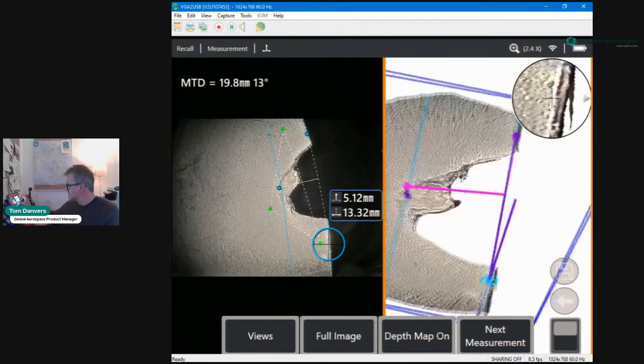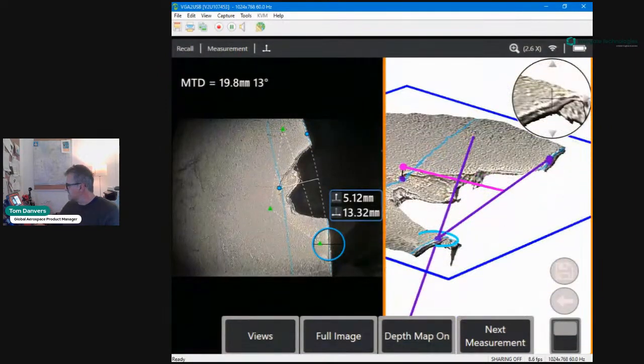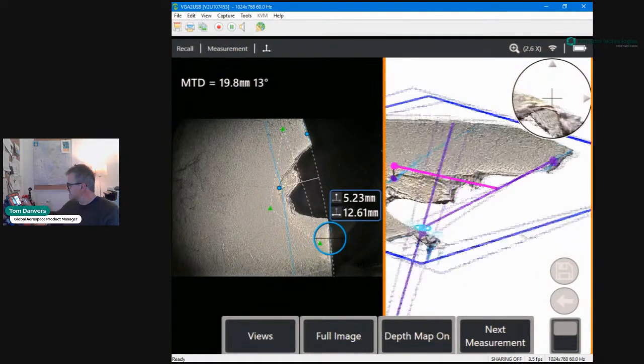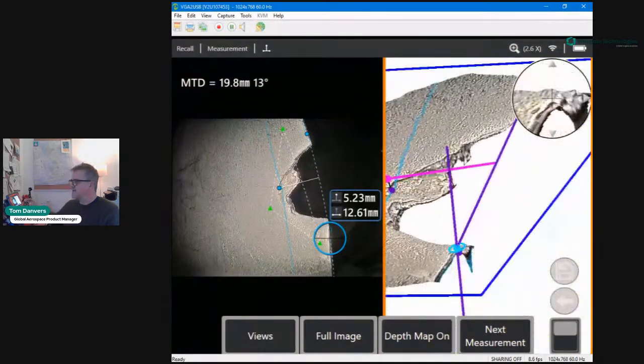And this is where you can work in the point cloud, and the use of guidelines is really important here. Less so on this blade, because this is a very thin sheet metal sort of surface, but we can talk about guidelines when we move to other measurement types. So that's how you would apply it. It doesn't matter whether you apply the measurement plane before or after applying the point align. But for completeness, I preloaded this image with the point align already applied, so you can tell the difference in the measurement type straight away.